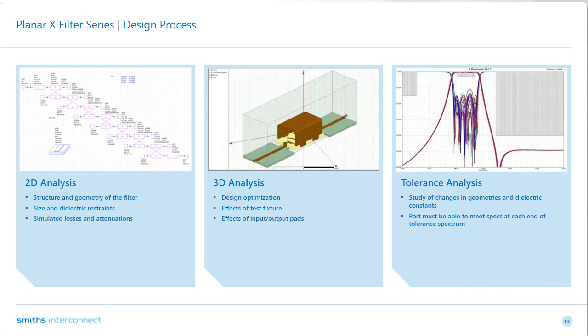The most important step in the process comes when the design is nearly complete. Once the geometries are optimized and the filter is meeting specifications, a tolerance study or a Monte Carlo analysis must be performed. This test exposes any flaws the design may encounter from different lots and tolerance stackups. There are thousands, if not millions, of different responses the printed filter may exhibit, from geometrical tolerances to dielectric constant tolerances. Every version must be simulated to ensure compliance of every filter.